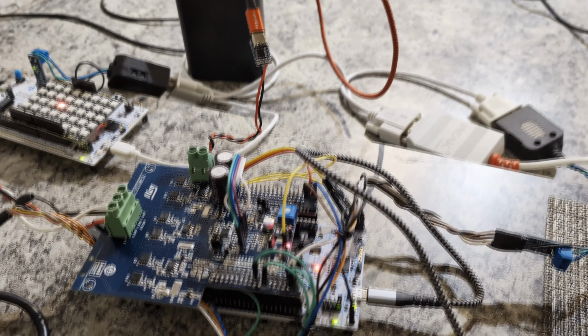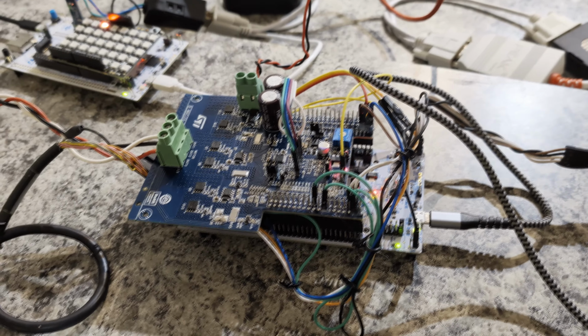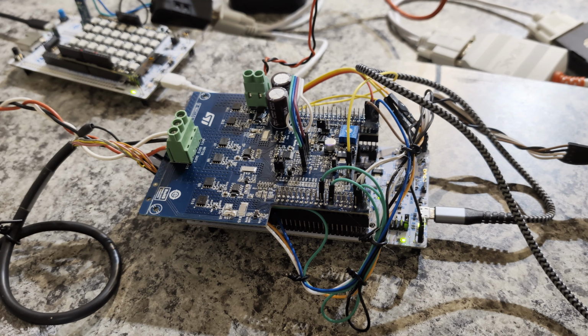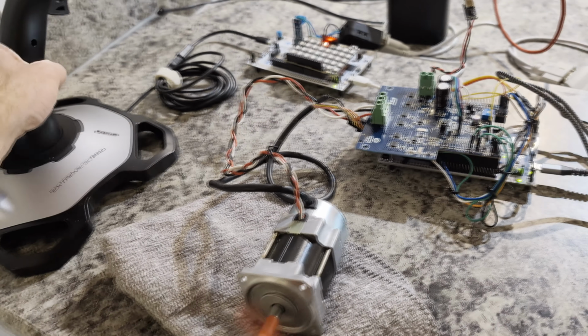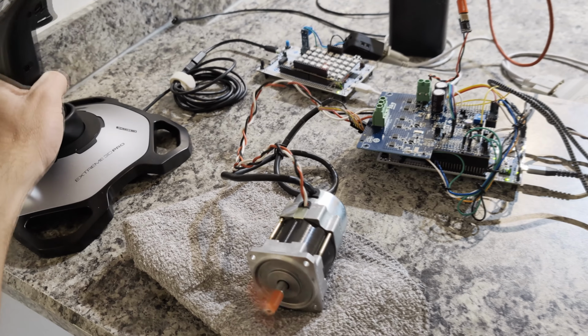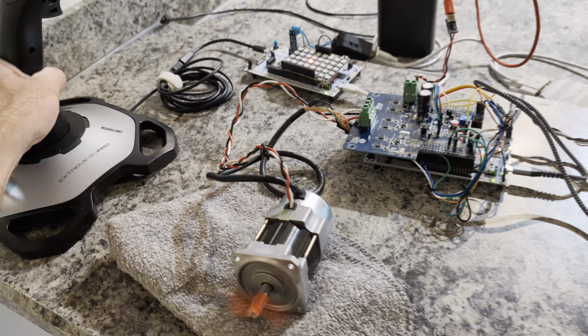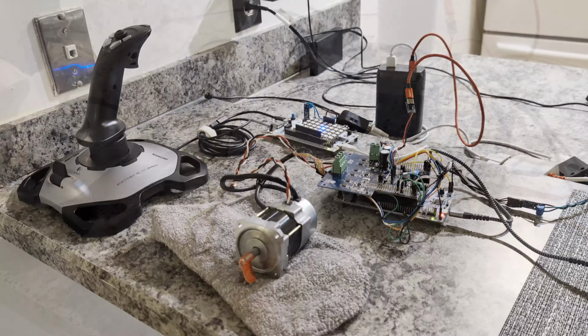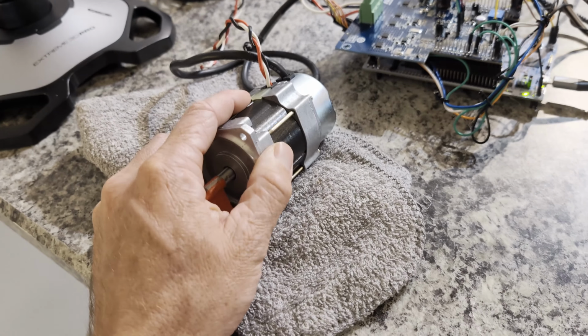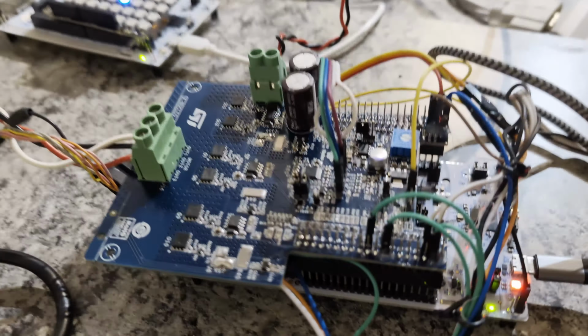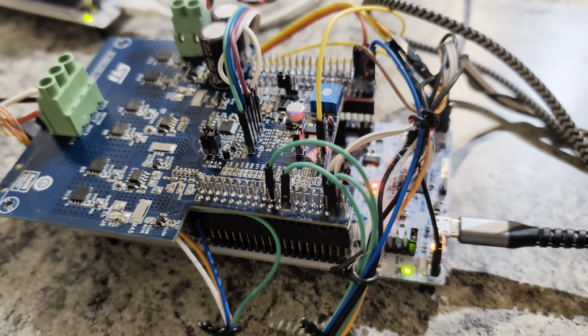Here we have the brushless DC motor driver board. It contains a full H bridge and some analog circuitry. It sits on top of the STM32H7 CAN nucleo board. The firmware for the STM32H7 is written from scratch by me and is developed using STM32 IDE. The velocity and the direction of the motor is controlled with the joystick. It uses CAN bus that comes from the joystick controller.